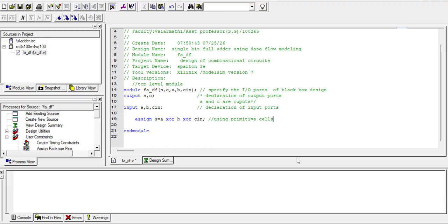Okay. So now in a short time I have given what is HDL, what is VLSI. Billions of transistors are built in a single IC. Why VLSI? Because of CMOS technology. What is CMOS? Combination of PMOS and NMOS. Why CMOS? Because of low power, we prefer CMOS. How do you get the low power? Because of reducing the switching activity, we are getting low power. That's why VLSI still stands using CMOS technology.